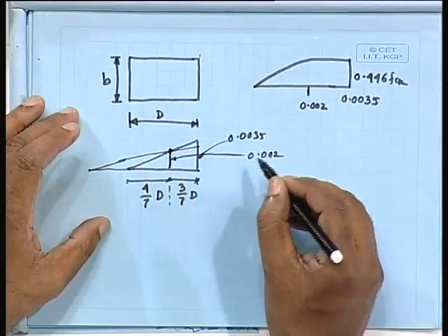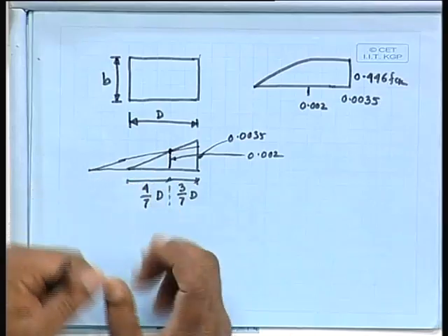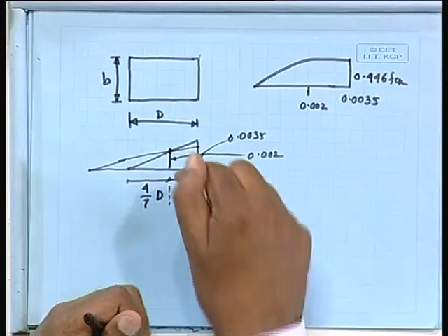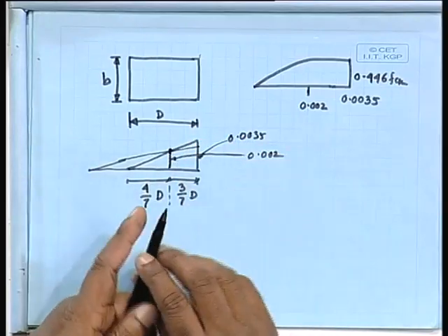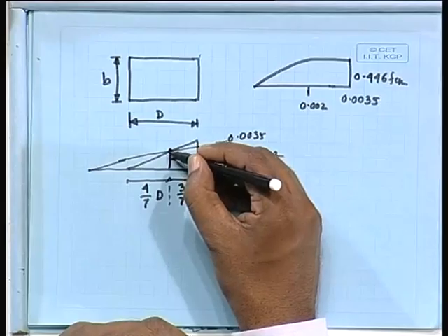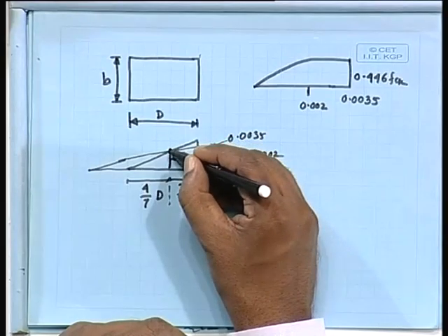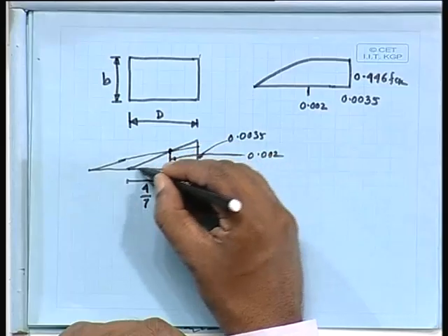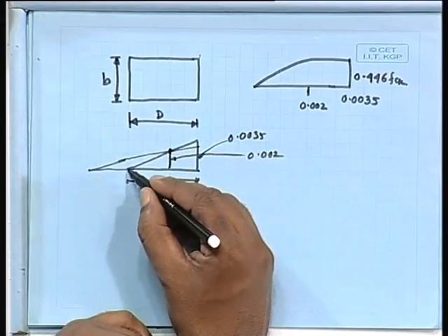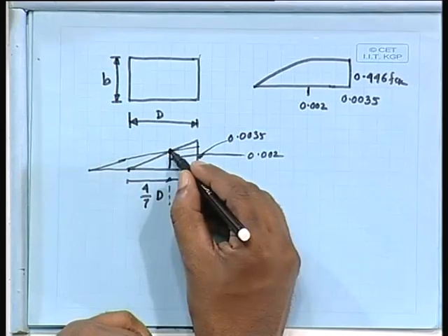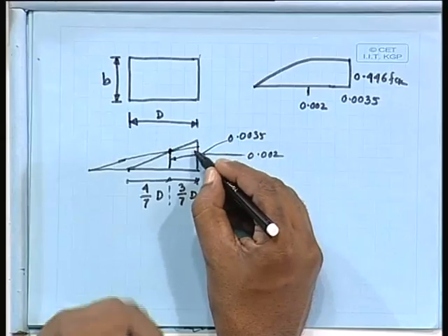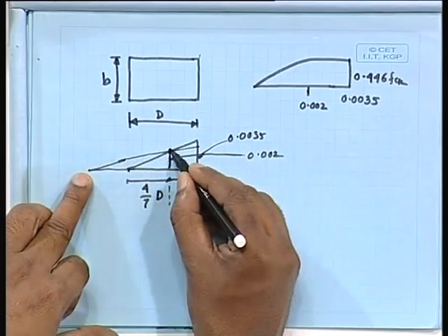This one, neutral axis is going outside the section. What I am trying to say, we have the bending moment and we have the axial load and bending moment. I know this is the critical point here at 0.002, this point. What I am trying to say here, as if with respect to this point, this line is being rotated. In other case, this is your neutral axis right now. So, if it rotates, it will never go beyond 0.0035.